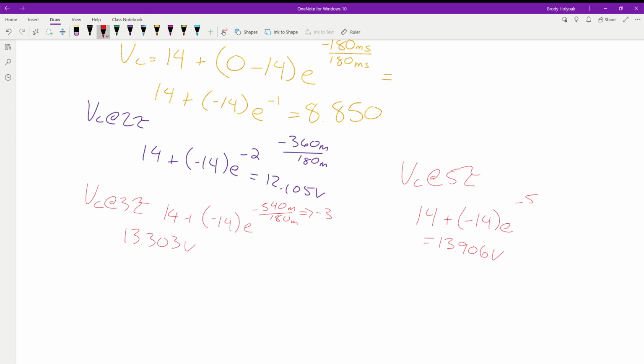Okay, so here's another question. So now that we figured this out, we can see what the value of our capacitor is. How much voltage do we have across the resistor at each of these points? We have the remaining, because it's going to split up. It's a series circuit. That voltage has to split up. So what we see is we don't just see a solid voltage value. We're going to see a ramp.